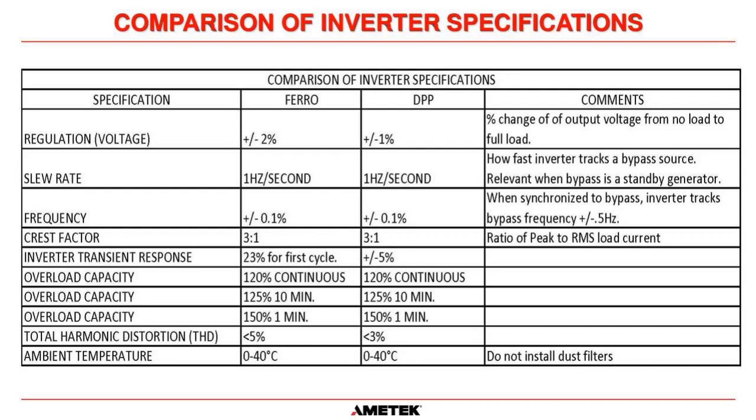Switching power supplies only draw slugs of current at or around the peak of the waveform, so they may have a crest factor often well over 2 to 2.5. And we set our overcurrent detection circuits to tolerate up to a crest factor of 3 to 1. So that's a really high peak current relative to the RMS current.